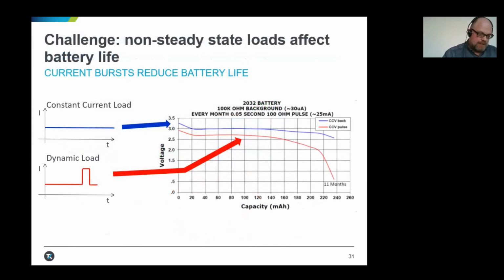So you've measured your battery's load current and you've determined an average value. You can then estimate battery life based on the battery manufacturer's capacity specification. Or, if you've used a battery simulator and have captured the load current in every operating state, you can determine a more accurate battery life.